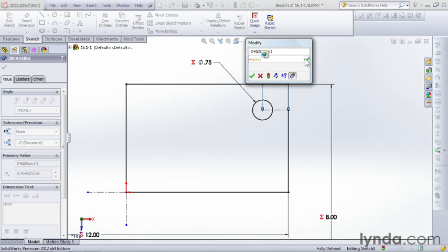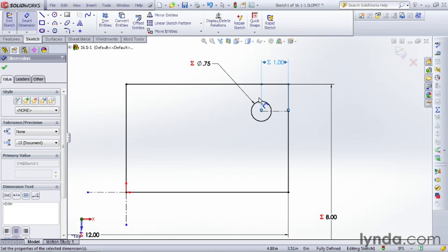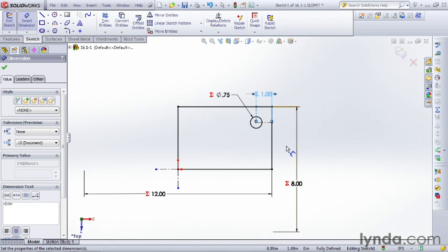Okay, and click OK. It's going to create a new global variable. And then we're going to change the value here to 1. Click OK. And now that links those values and adds that global variable. Now once we've got all these values here, everything is equation driven. I don't actually need to ever come back to this sketch. Right? Everything here is all linked value.